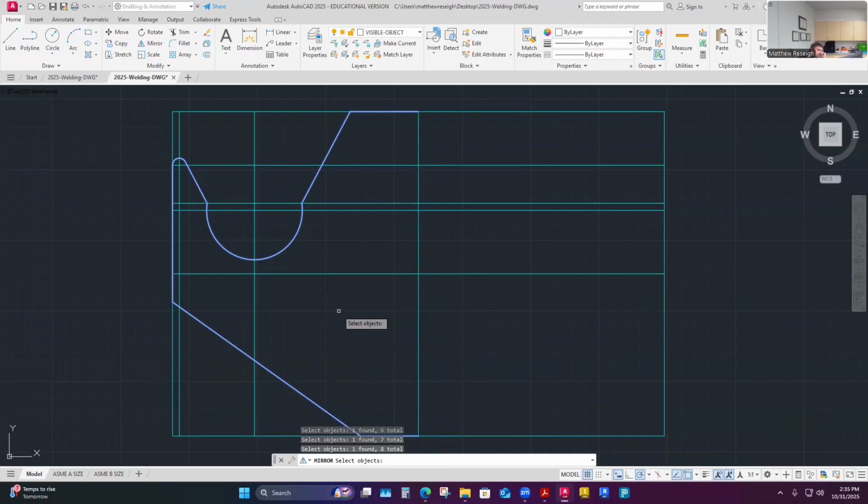And then it wants to know, okay, once you selected your objects, you'd hit enter because you're done selecting objects. So it's like, okay, I'm done with those. And then the next part of the command is specify the mirror line, and it's a mirror plane or a mirror line. And in order to create a plane or a line, you need 2 points. And so it's going to make you left click select. So I could left click the endpoints of my line.